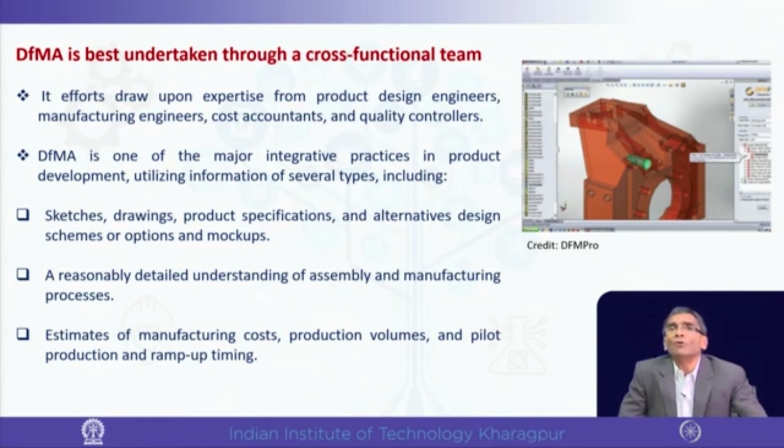Production volume is very important because it depends. If one has to produce one component, then naturally the process may be something else. For example, if one needs 10 pieces, one may go for machining, but when millions of pieces are to be produced, then people might go for casting, otherwise the machining would mean wastage of material and time both.